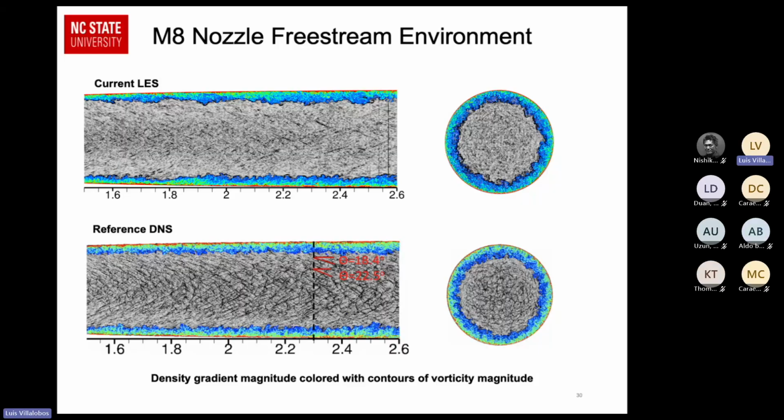Real hard question. How would you go to a complicated configuration? What would be the cost penalty going from 1D resolvent to 2D resolvent and arbitrary geometry? I think it's really not high in terms of computing 2D resolvent modes. There is a MATLAB library for doing 2D resolvent. It's called LinStab 2D.